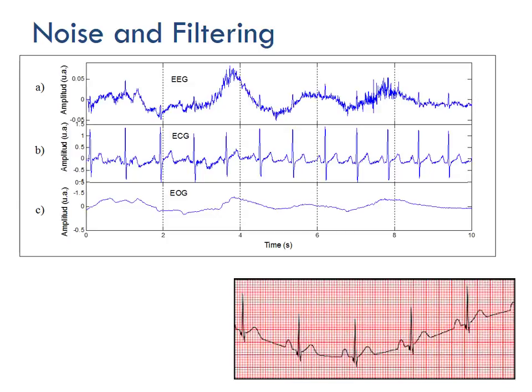And the signal that you want is the one below. So let's just say we take an op amp and we do a difference amplifier. We can take the ECG and we can subtract the noise. If we take this middle ECG reading and subtract the noise, you're going to get the reading at the bottom in pink, which is essentially the cleaned up and filtered version. So there's other ways of doing filtering too.